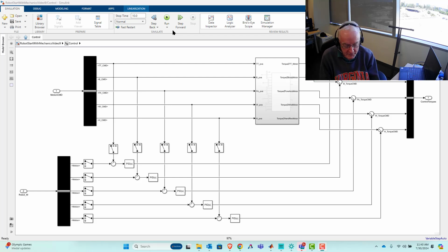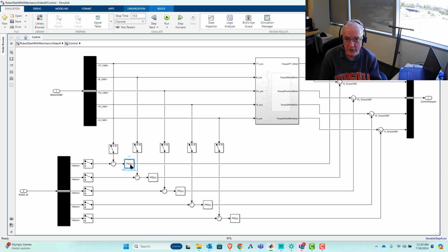All right. So from my perspective, though, I tend to think of discrete as almost meaning the same thing as fixed time step. And certainly the idea that you're going to do calculations, for example, on these PIDs. You can actually do numerical integration. I stands for integral, D stands for derivative, and you're going to be doing that sort of thing, right? But you're operating on numbers that in part are generated by hardware. That's the signal for angle for the turntable motor from the real robot when you implement this on the real system, right? And so as soon as you're getting into a calculation that's including real world, real-time measurements, the approaches of what you can do numerically will change completely. And that's where this whole idea of fixed time step becomes important.